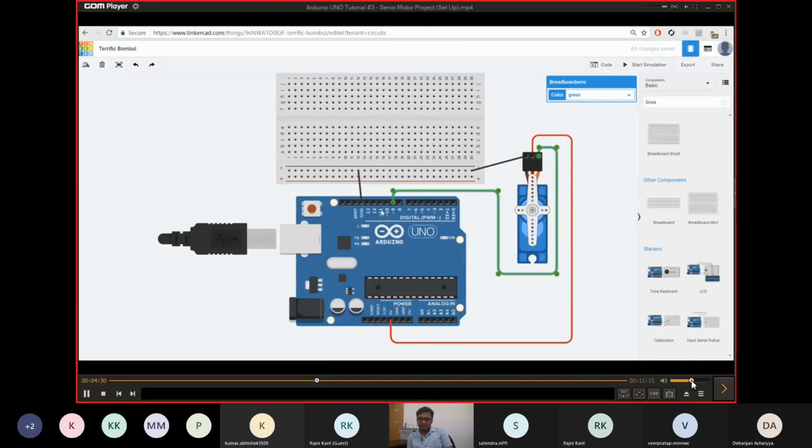This essentially turns your digital port into an analog port because it's varying the time of the on signal and the off signal to create a value, and then you can use that value to control things. So we can create the value of 0 to 180, even though in reality this can only go from 0 to 1, based on how often we turn the signal on and off. And because Arduinos and computers can do this thousands of times per second, if not faster, you won't even notice that it's doing this.